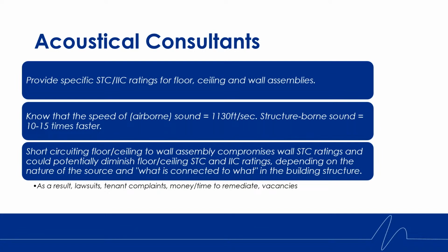So our trusty acoustical consultants through the design phase, as we all know, will provide specific STC and IIC ratings for floor, ceiling, and wall assemblies. STC and IIC for floor ceiling, and STC for the wall.